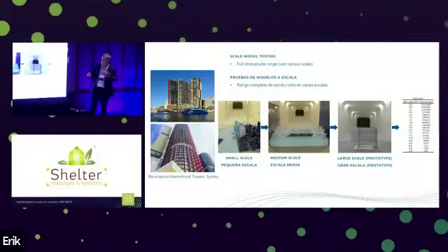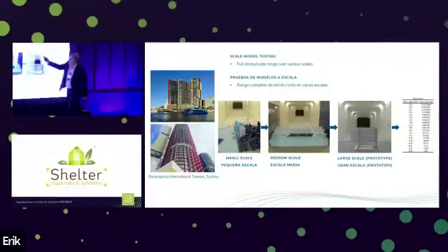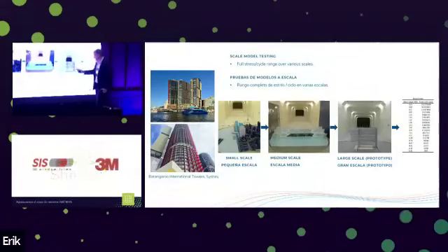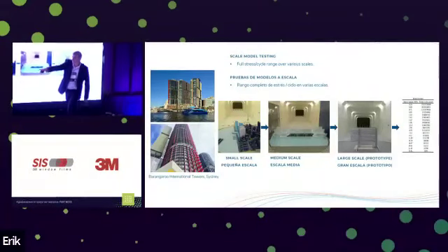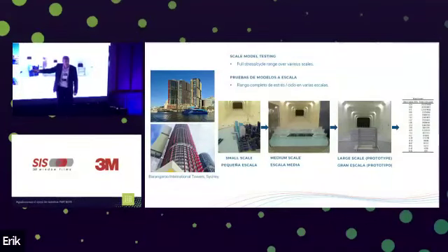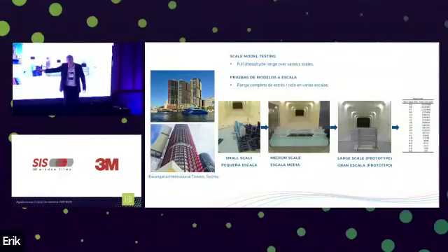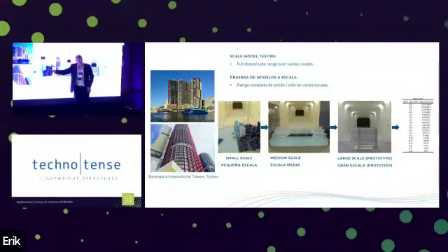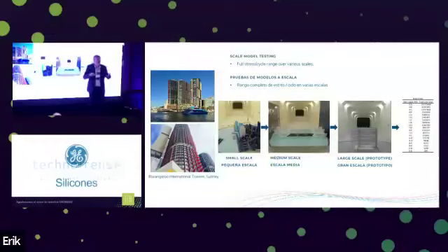Well, CPP devised a methodology. Actually, my colleague Graham Wood devised this. What it is, it's a combination of 3 wind tunnel scales. So this is Barangaroo International Towers in Sydney. This is a 1 in 400 scale model. And so we first of all do this test to understand the wind environment around the facade. We have a hot wire, we measure wind velocities and wind direction. We get what's called a Weibull distribution. How windy, how often, and from what direction.